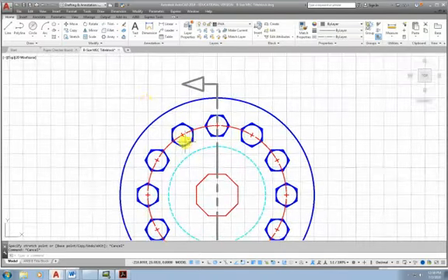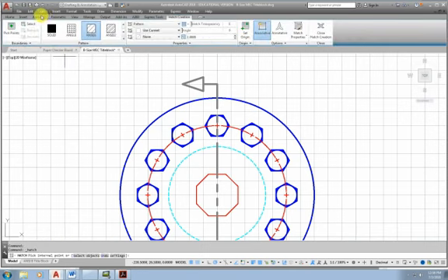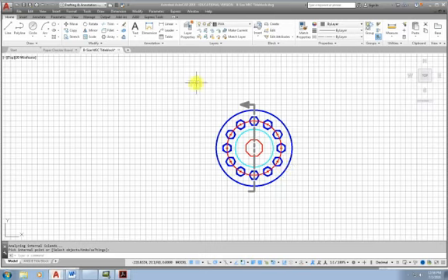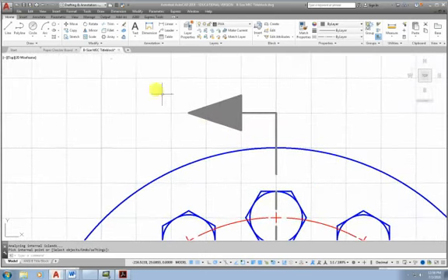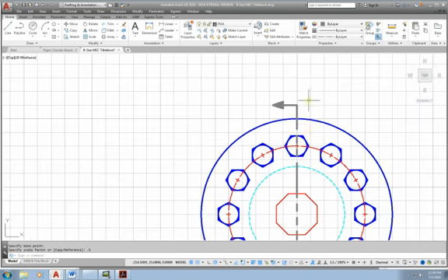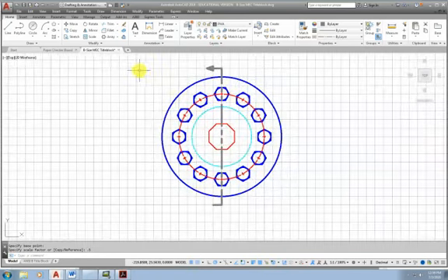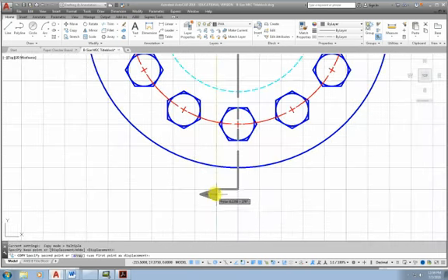Once I have one of them, I'm going to fill it, and then I'm going to copy it. And so I'll come back here to my hatch pattern, choose solid, drop that on there, close it. It's a little big. I'm going to scale it in half with a blue window from here. And this is just perfection tendencies. There we go. There's not a bunch of big rules, but it is somewhat of an artistic expression in your design work, and so I like to make it the way I like it.